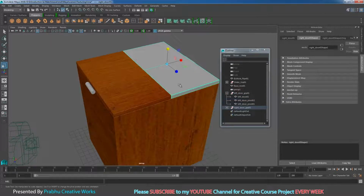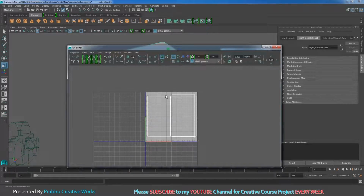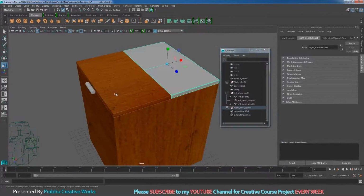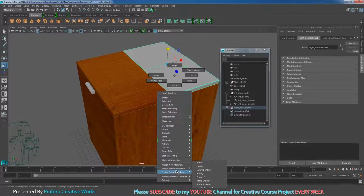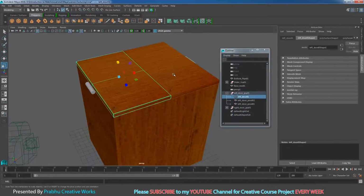So when I select this one, go to UV and choose UV editor. It is also perfectly aligned as we did for this. Now you want to apply the same material to this one. Right click and choose assign existing material. Don't choose new material, assign existing material. Here you need to choose door_blend01. Now it's perfectly textured like this.